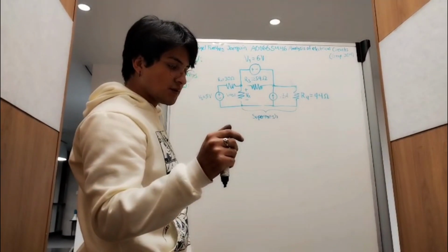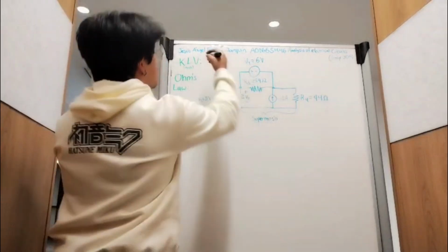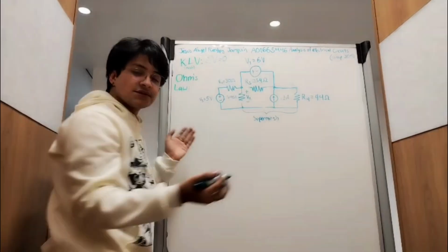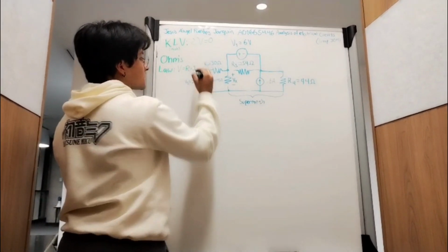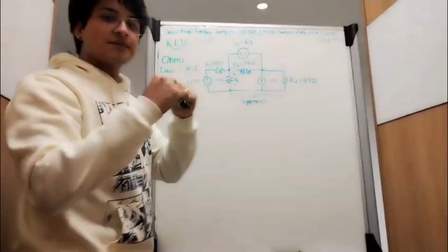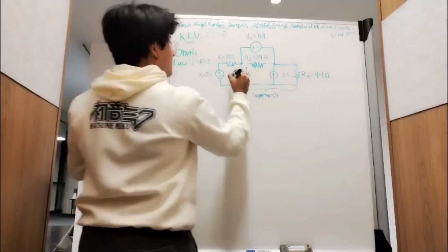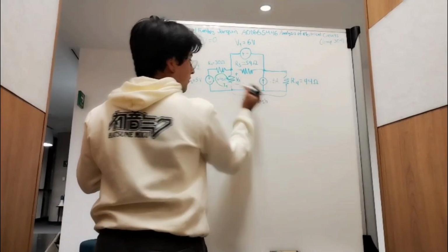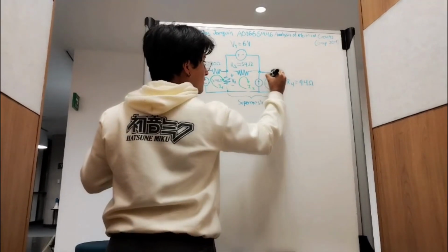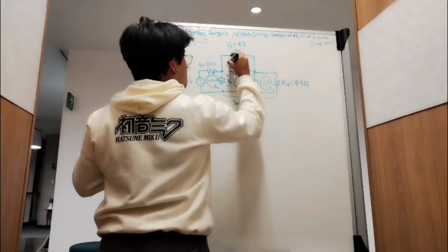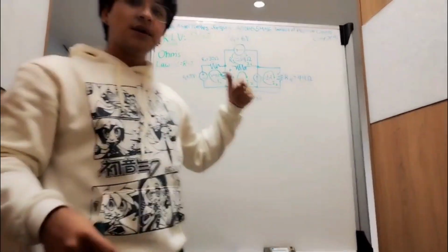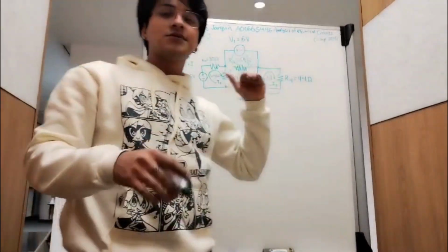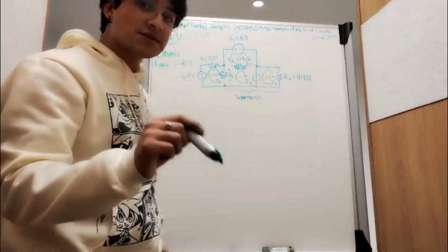So in this case, we need to be working with Kirchhoff's law of voltage. It states that the sum of all the voltages is going to be equal to 0. And Ohm's law that states that voltage equals resistance times current. Current defined as I. So in that same line, we're going to be defining I in each one of those meshes. First, we have I1, I2, I3, and I4. The way that the current is stated here is just a proposal, because further we're going to realize if that direction is actually the real direction in which the current is behaving.